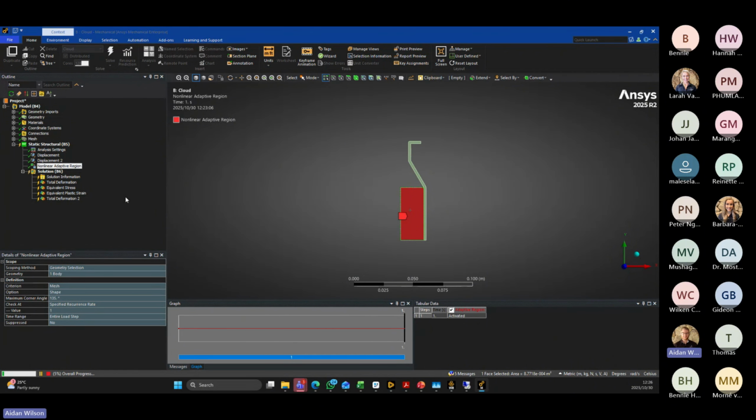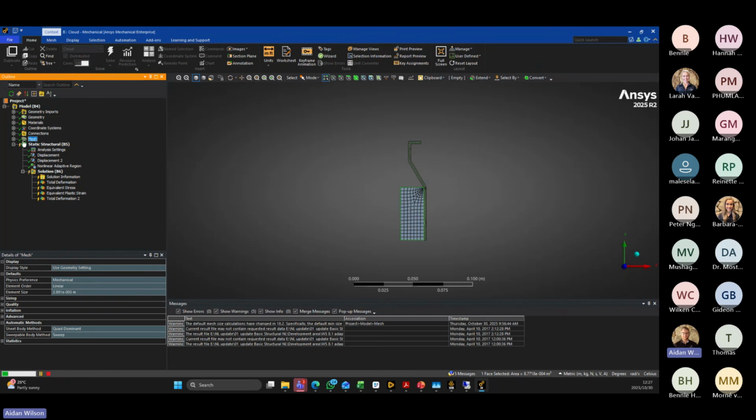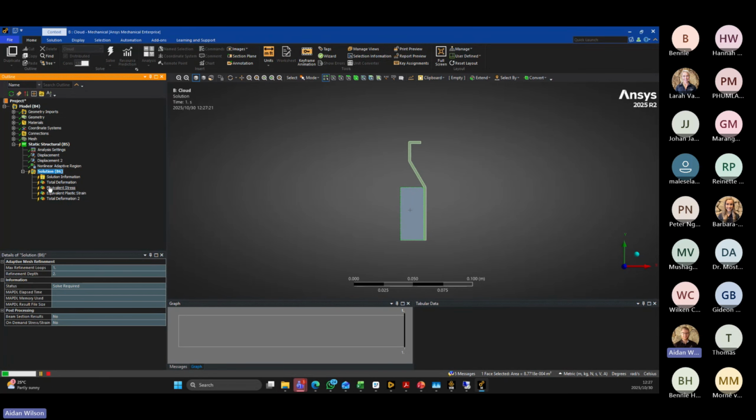So from here, Ansys Mechanical is going to recognize that I've chosen the cloud as my solver. From there, it's going to say, okay, in order to simulate, it needs the files. So you'll see over here at the moment, it's uploading files. This is essentially uploading my simulation, right? It's also important to note that the mesh had to run first. So we still have to generate our mesh locally, at least in Mechanical. This won't be generated in the cloud space. We're only focused on the solution when it comes to the cloud solving.